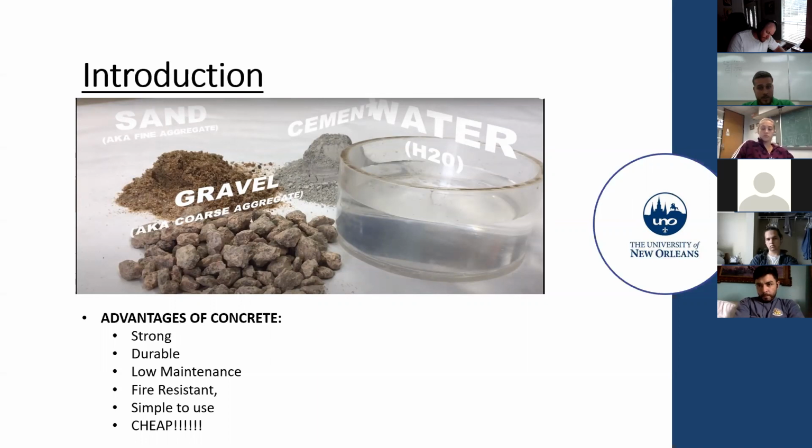In fact, as long as you avoid washing out the cement, concrete made with Portland cement can be placed and cured completely underwater. It will set and harden just as well, and maybe even better, as if it were placed in the dry. So if you have more water, it's even better, as long as you don't wash out the cement, because you need two important constituents, cement and water, as they act as a glue. Other aggregates such as sand and rock are bound together with the help of cement and water.